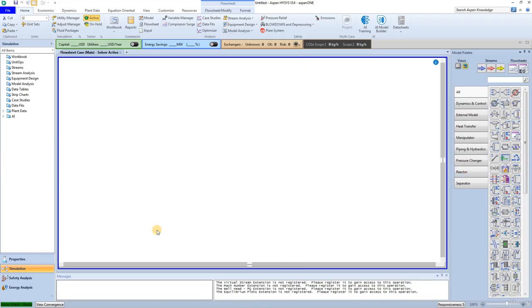As we highlighted before, the LNG process model includes the following units: acid gas removal, dehydration, propane pre-cooling train, compressor train, and LNG section. These units will be modeled in Aspen HYSYS using the sub-flow sheet operation. Each sub-flow sheet will then contain the unit operations that comprise that unit. We will begin by building the structure of the overall flow sheet using sub-flow sheet operations.